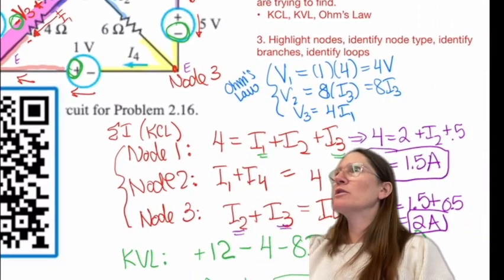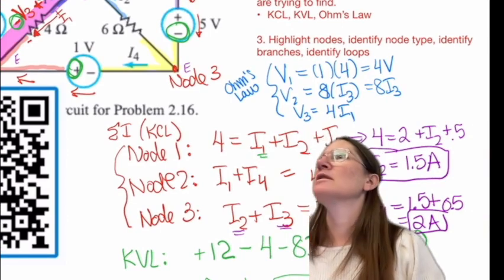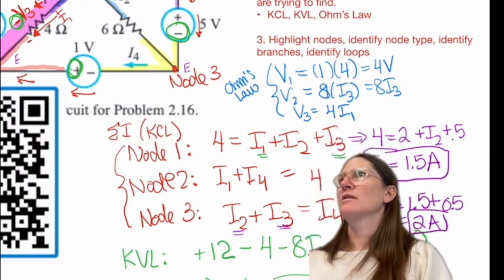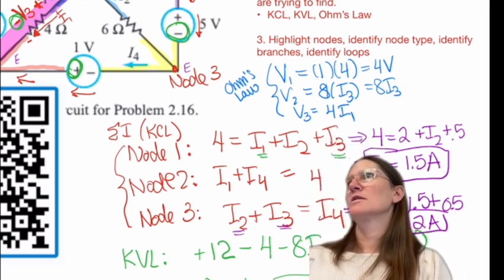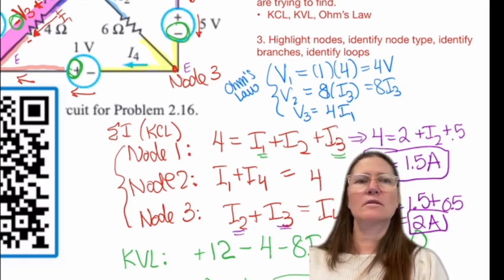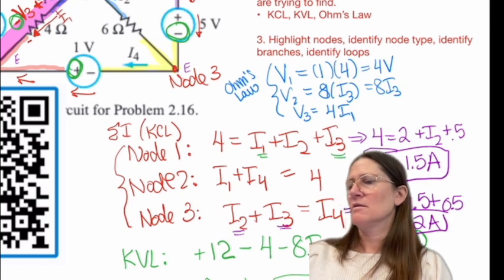All right, was there another question? Yes. Yeah, two. So the direction of current we just assumed off the given current, correct? Correct. And then for when you use KVL, since the 5-volt battery polarity switch, it basically acts as a voltage drop.